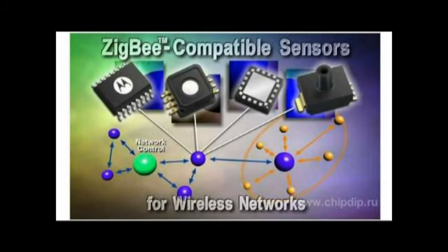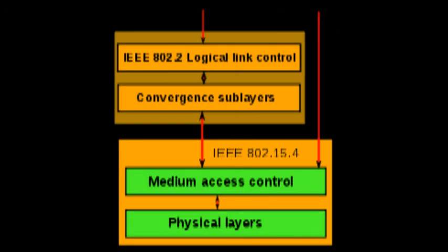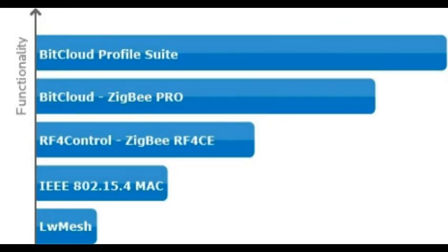Zigbee is not intended to support power line networking, but to interface with it, at least for smart metering and smart appliances purposes, because Zigbee nodes can go from sleep to active modes in 30 milliseconds or less. The latency can be low, and devices can be responsive, particularly compared to Bluetooth wake-up delays, which are typically around 3 seconds. Because Zigbee nodes can sleep most of the time, average power consumption can be low, resulting in a long battery life.